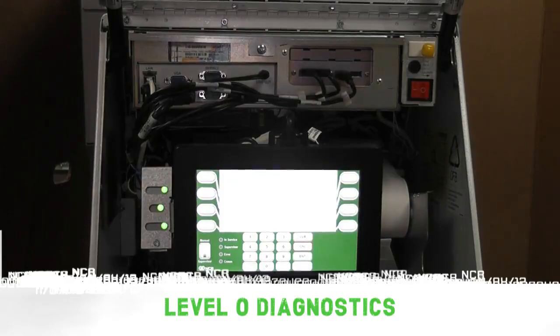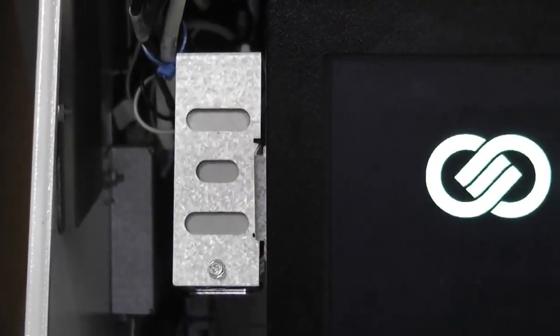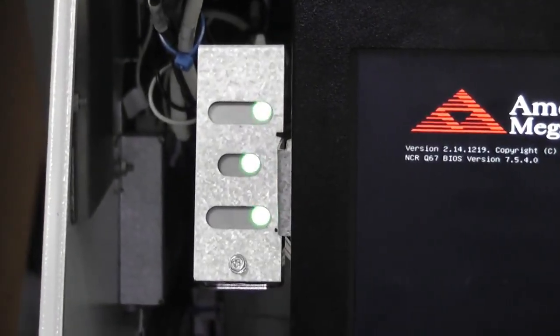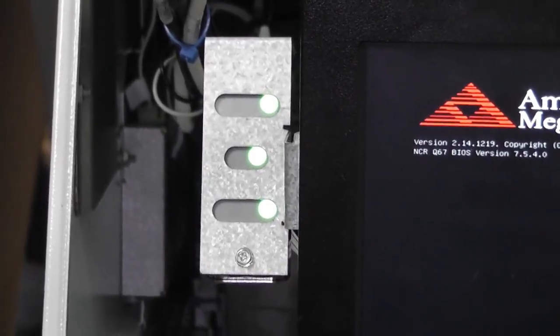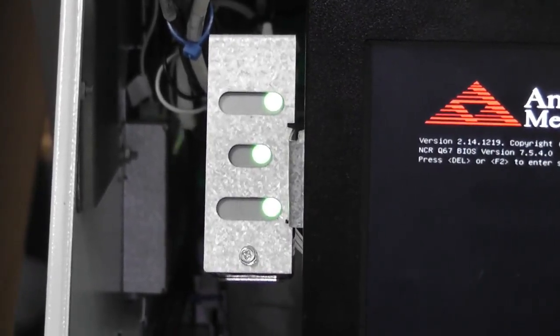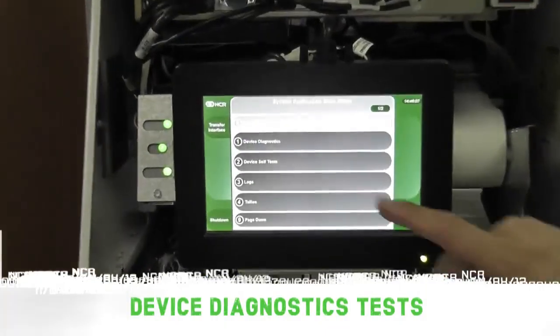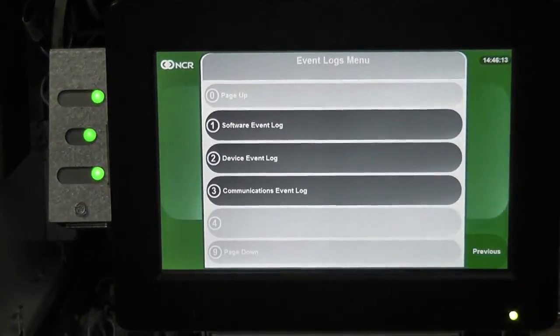Level 0 diagnostics provide an overview of the general health of the BRM upon startup. At startup, the amber and red LEDs in the overall status indicator lights are off. The green LED flashes 4 times per second at startup during Phase 1, when the main control firmware is executing. The green LED turns solid after startup during Phase 3, indicating successful mechanical initialization. If anything goes wrong during the startup process, the appropriate LED turns red to indicate a problem. For specific diagnostic information, see the Device Diagnostics section in the BRM Service Manual.